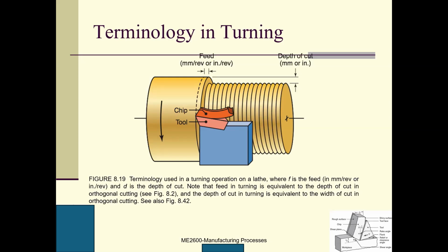What I want to test you on is how we can do experimental orthogonal cutting. Approximately, this is orthogonal cutting, and the answer is to use a thin-walled hollow cylinder. That's the keyword, okay? If you don't give me this keyword, wrong answer.